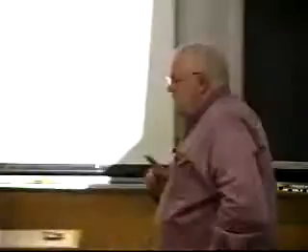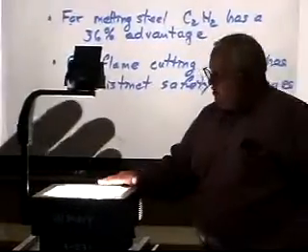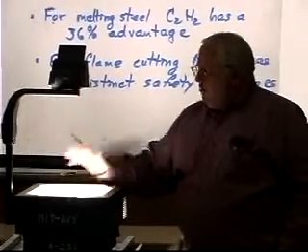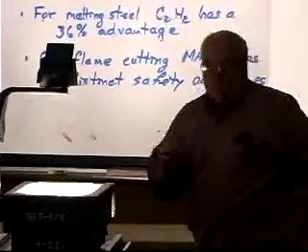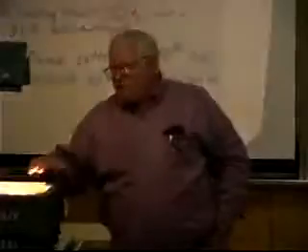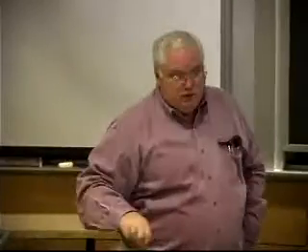Not necessarily for cutting, okay? And we'll get to cutting, we haven't talked about the process, but MAP has distinct safety advantages. What are the safety advantages? Well, one of the problems with acetylene is that if you try to compress it at 50 psi or something like that, it goes boom. It compresses it under pressure.